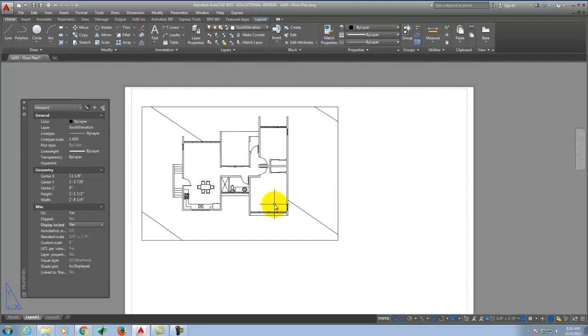So I have my scale set. I'm suggesting drawing at a 1/4 scale. 1/4 inch equals a foot for this. If your drawing doesn't really fit, once you get the elevations up, etc., change it to 1/8 scale or change it to whatever scale seems appropriate to you. I'm not married to it having to be 1/4 scale. I just think it's a good place to start. So I have my drawing shown here.